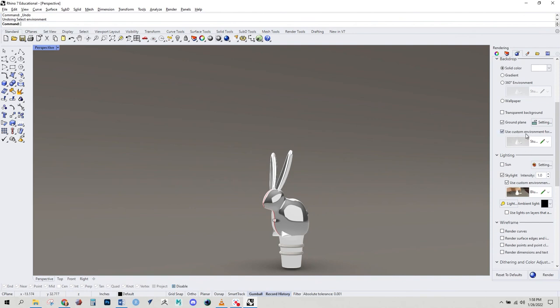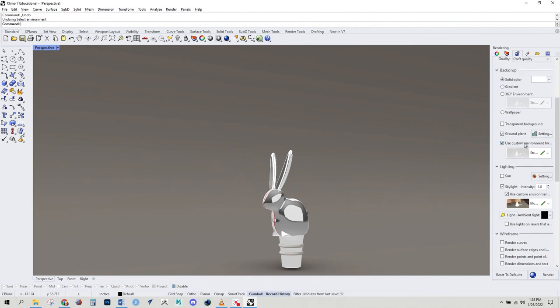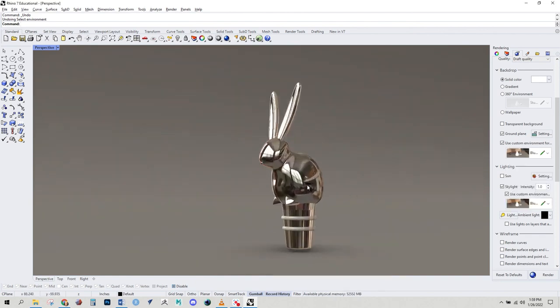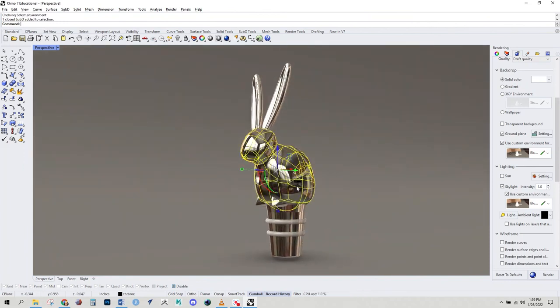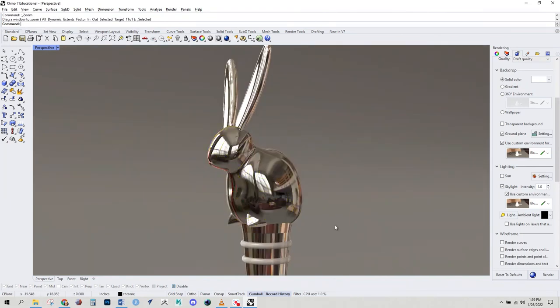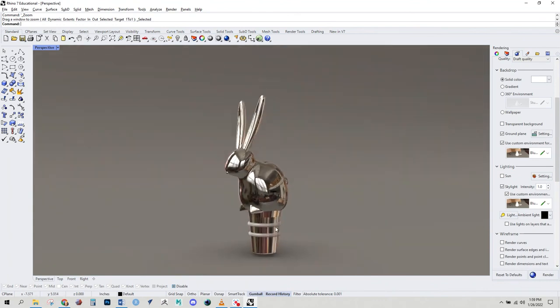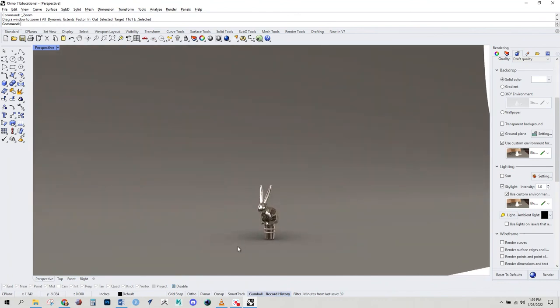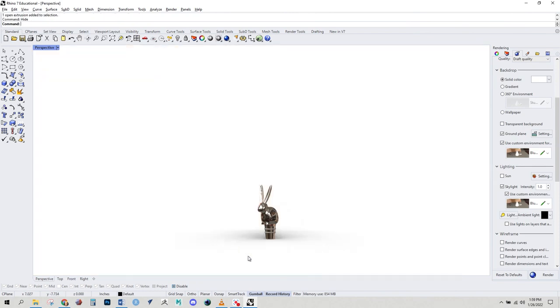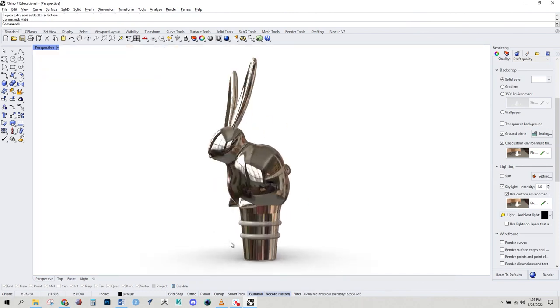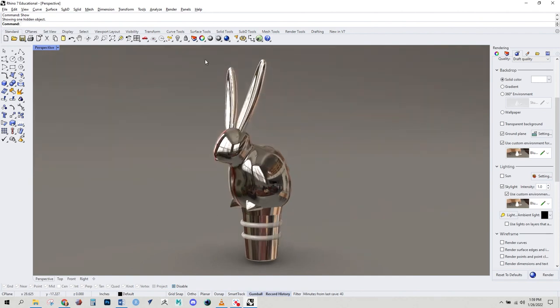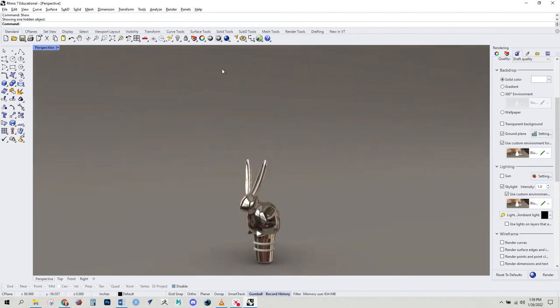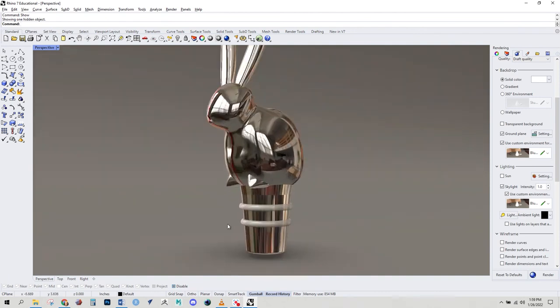Let's also set the backdrop to use that same image. So we'll go to Blur Loft there, and that looks much better. Let me ZS to put this in the center. And just so that you can see what the sweep is doing, if we take this and hide it, it gives us this infinite space with a white background. This can be okay too, but I like how the sweep has a little bit more of a kind of gradient as it goes back in space.